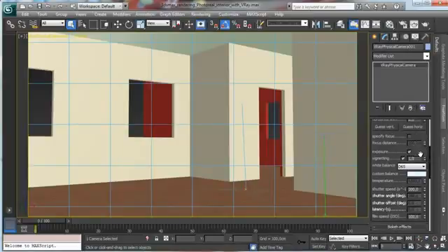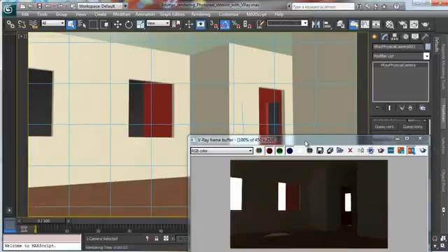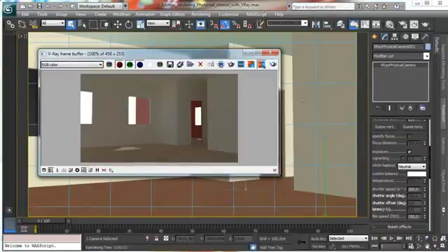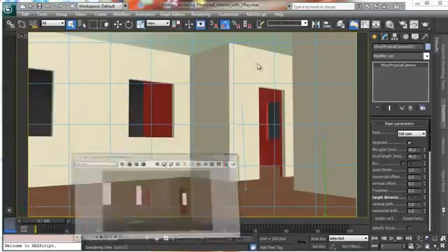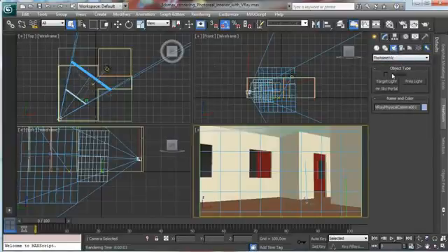Let's go to see the exposure, and I like to add no vignetting for the moment, and the white balance will be neutral, so we use a white balance without coloring. And then let's say that we have 250 ISO. Let's render again. Okay, and let's check with the RGB. Okay, we can try now to have another lighting just to see the differences.